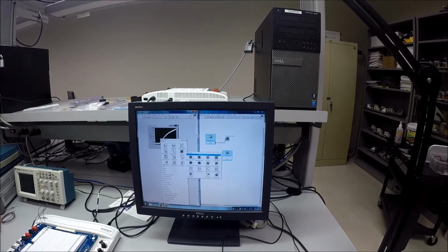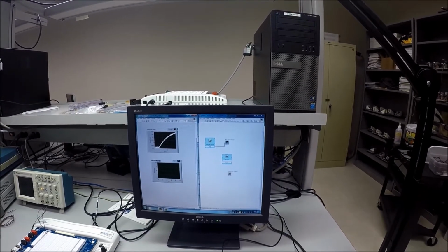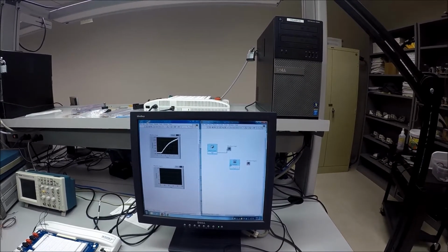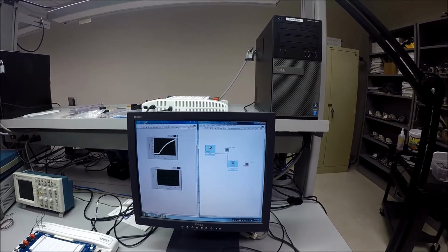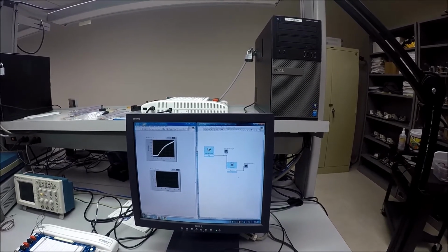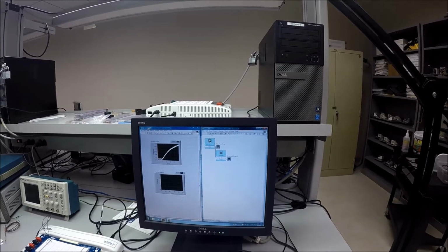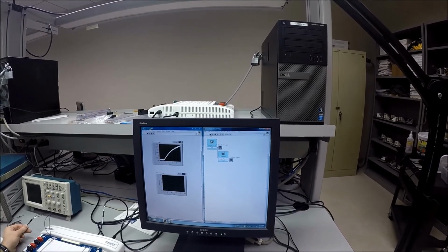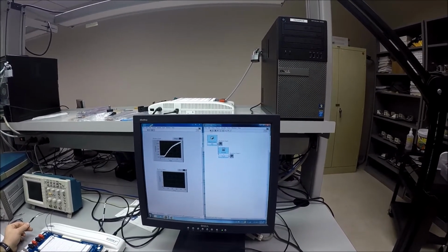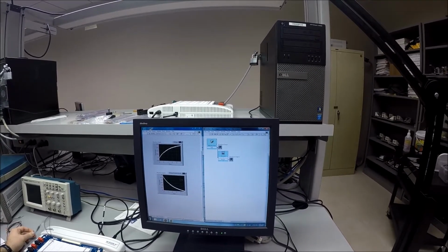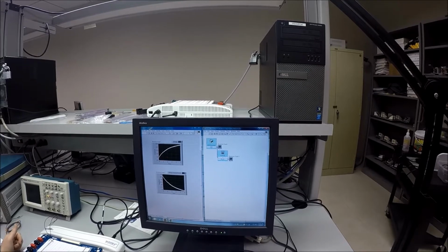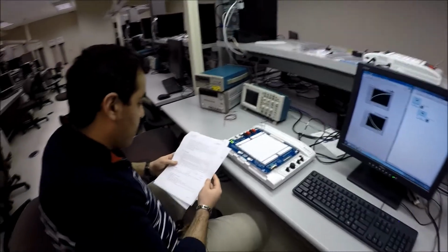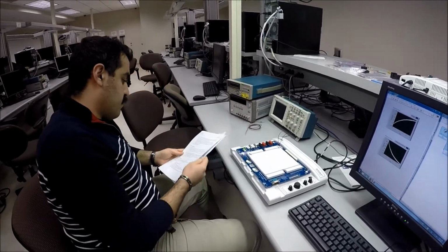We need another waveform graph to actually show the temperature. We wire the data to the V of this formula, which is the input of this, and wire the result to the waveform graph. You can also hit Control U to make it nice and neat. Now hit the Run button again. Now this is our temperature and this is our voltage. So this is for part 1. You have to redo this experiment with a couple more temperatures. That's it.